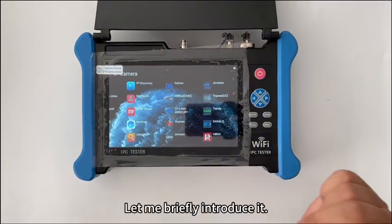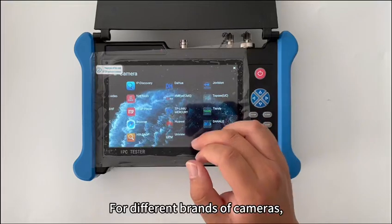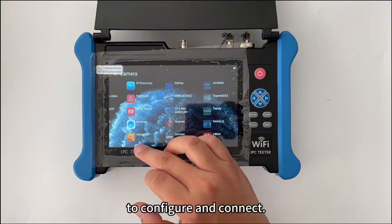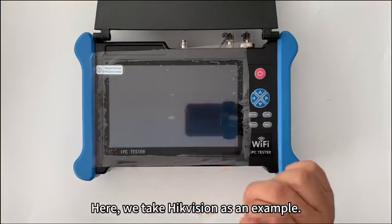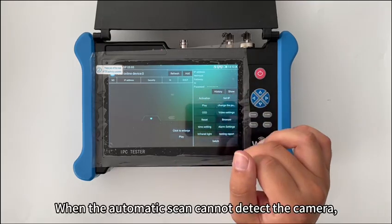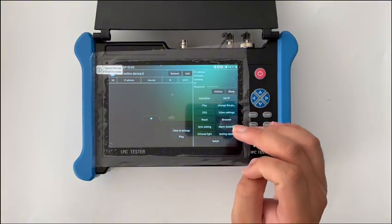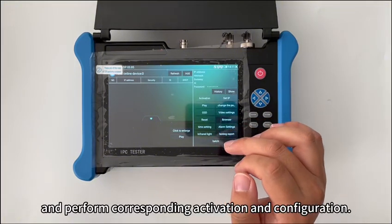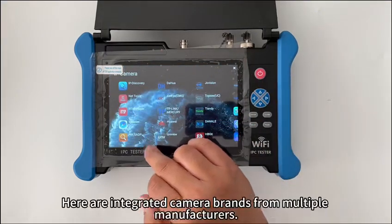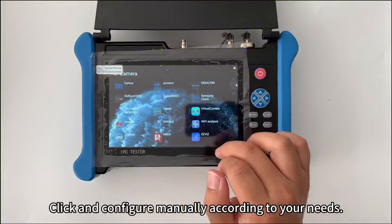Let me briefly introduce the app for connecting cameras from multiple manufacturers. For different brands of cameras, we can click on the corresponding brand's camera app to configure and connect. Here, we take Hikvision as an example. We can enter and see the relevant configuration. When the automatic scan cannot detect the camera, you can manually configure the corresponding IP sequence and perform corresponding activation and configuration. Here are integrated camera brands from multiple manufacturers. Click and configure manually according to your needs.